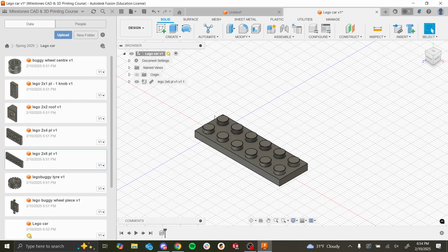So your first part will always be grounded, right? It's kind of like making an origin for your assembly, and it just places it and fixes it in place. So it's kind of like the 3D version of the fixed constraint. But it's okay for the first part because you want everything else to move in relation to that foundation, right?